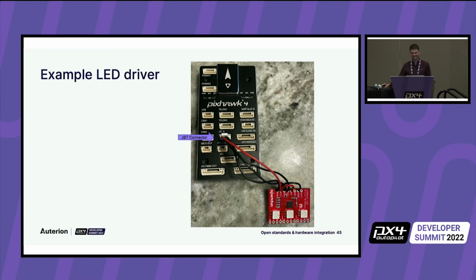So I took this thing, soldered on the cable, which has a JST GH connector on this side. And now we can plug it into a Pixhawk. And that's what I did. So here, it's now plugged into the I2C port, a standard port on the Pixhawk. And it's not doing anything, so we need to write a driver. All right, let's get going.